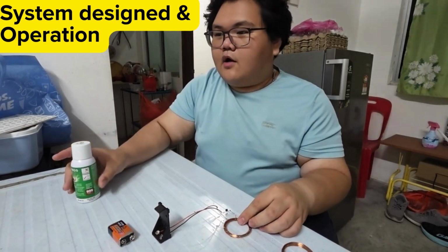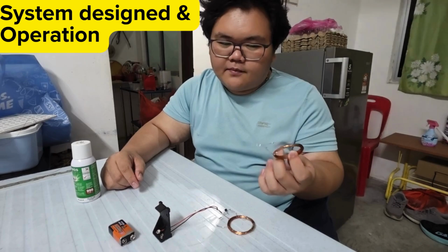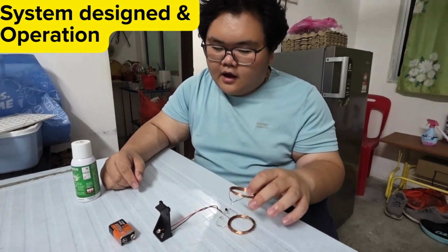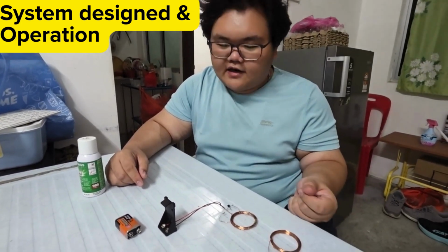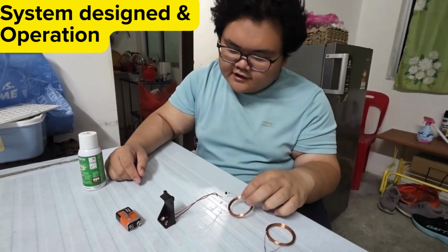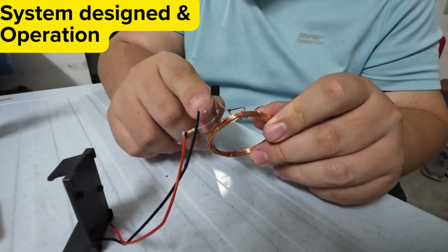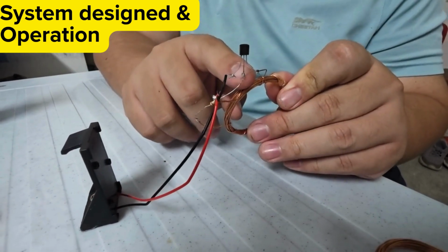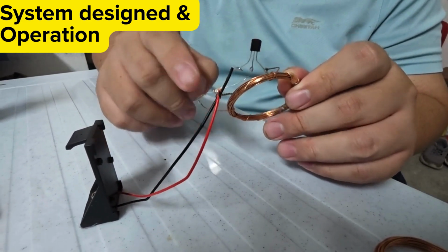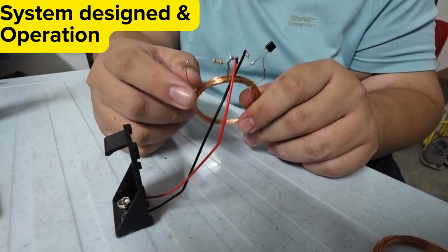We know that for power to transmit wirelessly through induction, we need a time varying magnetic field. How we achieve that is by using a transistor here. This is a 2N2222A transistor. We connect the base here to a 10 kilo ohm resistor, and then from the resistor to one end of the transmitter coil.